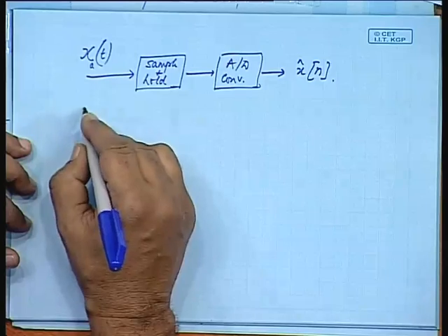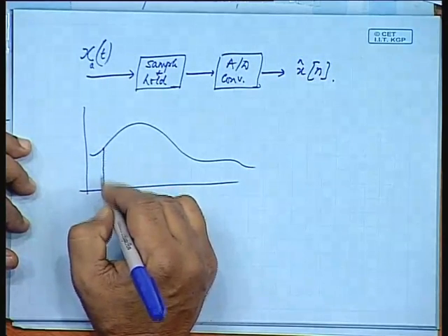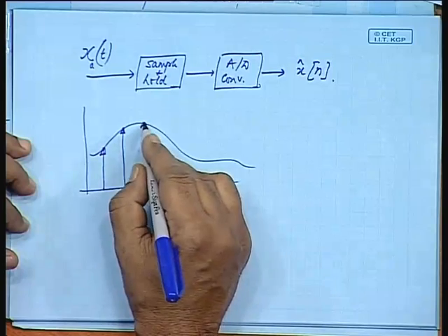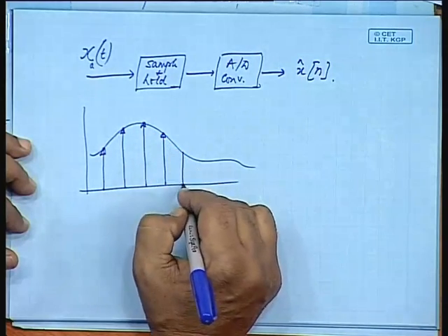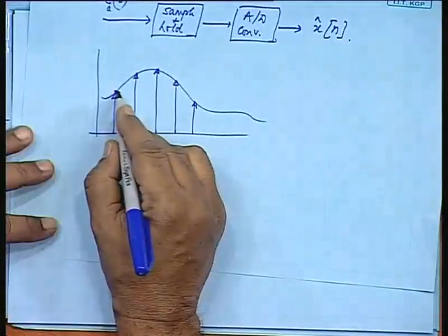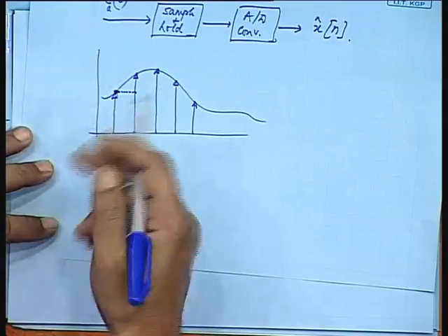Now, the analog signal may be like this. If you just sample it, it is not an instantaneous process. We sample it, but then this sampled value will be represented by binary digits by any particular code, and till that particular value is approximately close to that sampled value, it will not stop. So, it will require continuously a fixed input. If the input keeps on changing, then it will be disturbed. So, this level has to be maintained for a period T. This is the sampling period, and within this time the computation has to be completed.